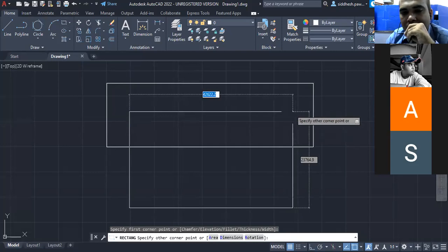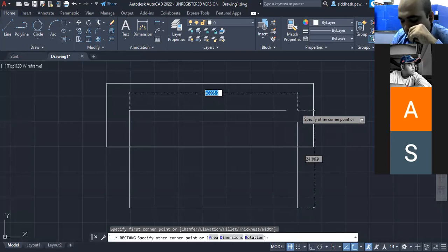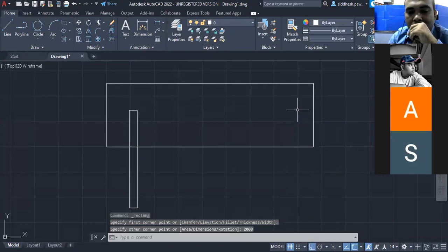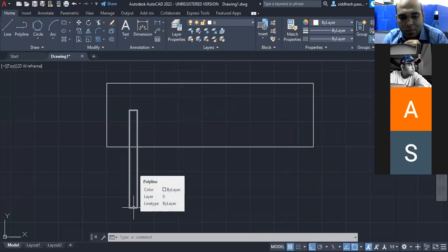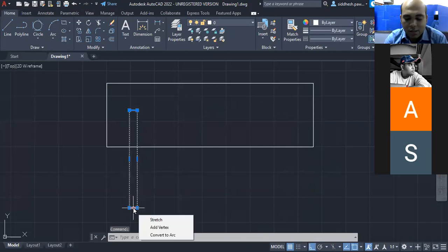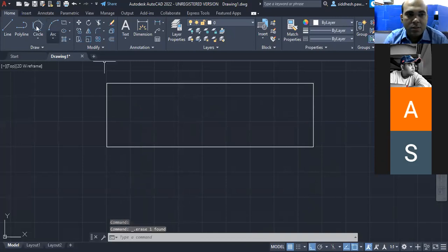It means that if I want to do it manually, for the length of the rectangle, let's take a length of 2000. I press 2000, enter. That means it is showing that you agreed with the next dimension, and you have taken this as 2000. Once again, I'll just repeat how it is done. Just have a look.